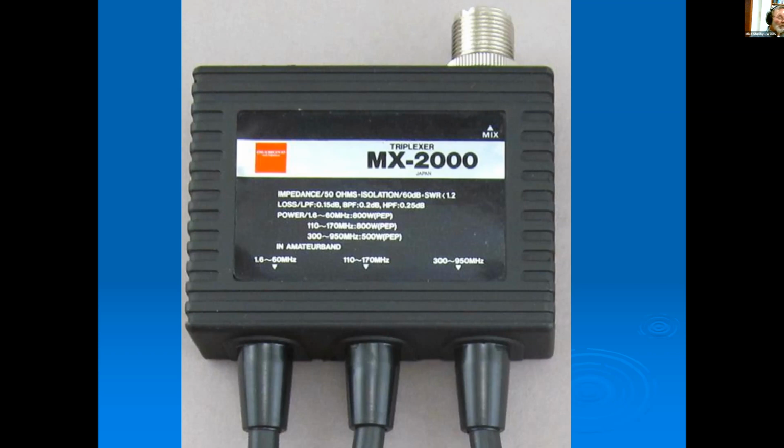So one of the things that is kind of interesting, I've seen people try and keep their coax costs down. When you deal with LMR 400, that can be some pretty expensive coax. So they'll just run one piece of coax out of their shack. They have another duplexer back in their shack to use your 220 and 2 meters all combined on one PL259 out the back of your rig.